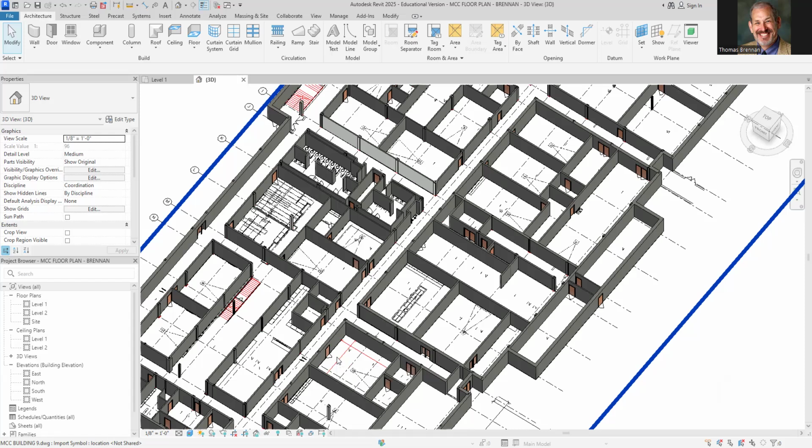Yeah, for 154, I don't know if this is a wall partition. Never leave an opening for your doors, always just run the wall right through it, because if you do that, you're just going to mess things up. So you just run it right through all the way. Yeah, you're doing good, that's it. And then just run this one too. Some of this is learning how to read blueprints too.